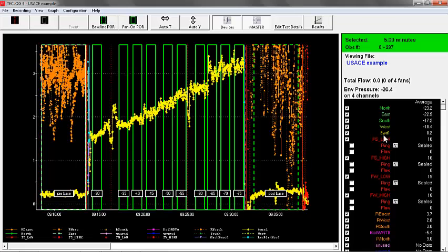So we're showing our 2 baseline periods of record, where if I click in this first baseline period of record, it's showing this yellow one at about 0.2 pascals. I'm going to click on our post baseline. Our post baseline was about 0.3, so 0.2, 0.3 for the average of that 2 minutes. And then if I click in on this, this is where an induced pressure at -30, our yellow here is at 1.6. So we were at about 0.2 to start with. We went to 1.6, so we've changed by about 1.4 when the building changed by 30.